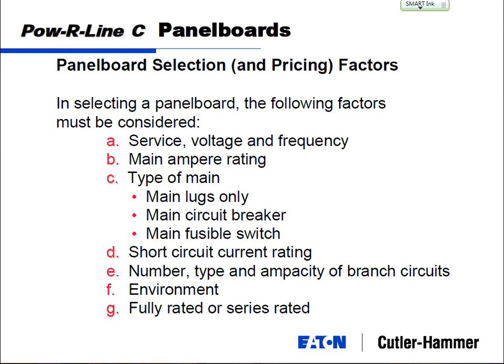Consider ground reference to be voltage 0. This is the way you have to look at that. All your voltages, 120 or 480, are all referenced off this ground voltage. So in some cases, you may get a fault condition if you don't have a neutral, where the ground voltage is going to change, and that could throw off everything in an ungrounded system. It could throw all your voltages off and your whole system can get out of whack. So generally speaking, you always need some kind of ground reference.